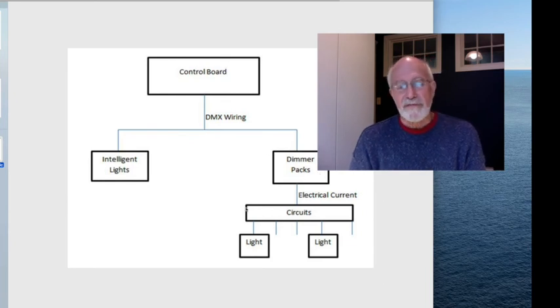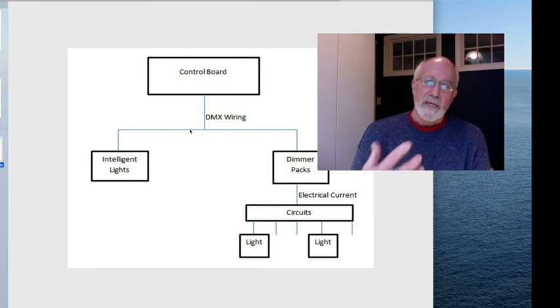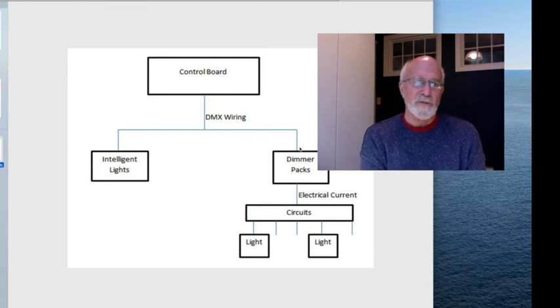There are things missing from here. So, for example, there's permanent power going to the racks. There's permanent wiring going out to the ceiling, lots of it. One complete circuit for each numbered circuit in the ceiling, coming from each numbered dimmer in the racks. There are permanent in-the-wall wiring setups for the computer data, and then we connect into that and run it to temporary components or routers or distribution components, and then connect the lighting instruments up to that.